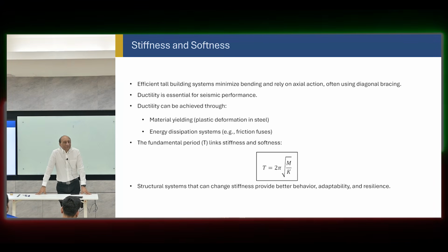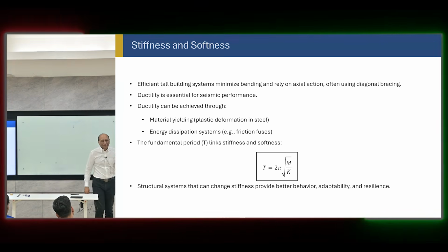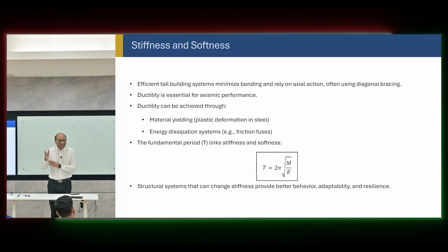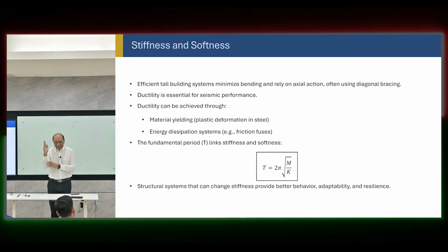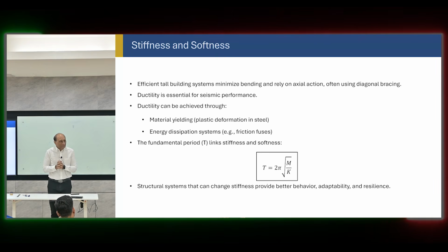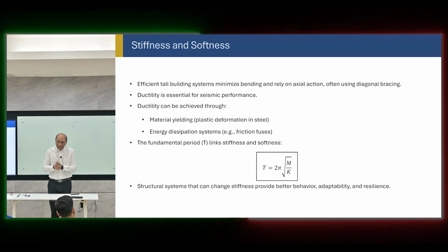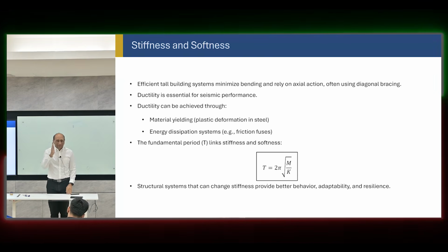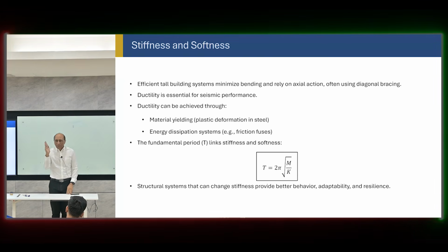Acceptable natural period of a tall building. For 300 meters, it could be as long as 8 seconds. So once again, just like your estimate of the displacement, the estimate of the natural period is not so good at this point. So imagine 7 or 8 seconds it will take for the building to complete one movement.